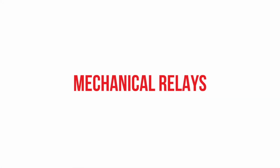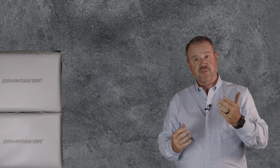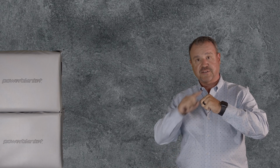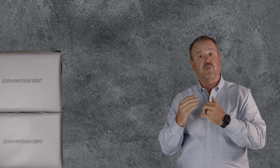Mechanical relays are a relay that make and break voltage to a heater. In other words, they get a signal from the controller and then the coil is pulled in and the mechanical relay makes contact and allows the voltage to flow through the heater and back to the circuit. So just like a valve, or just like a lot of times people compare electricity to water, it opens and closes that gate to allow voltage to come on and come off. These relays have been around for a long time and they work great for low accuracy, high volume type applications, but they do wear out.